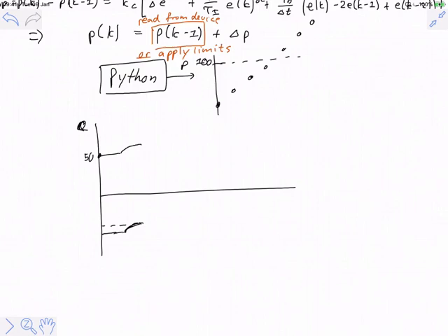Once you have satisfied yourself that those boundary conditions hold, in other words, that when you do it on a smooth system, under these controlled conditions, the values don't saturate and so on, then you can implement a larger step change which saturates your output, and then you can clearly observe the difference between the position and the velocity form. It's the only way that you can check the difference.